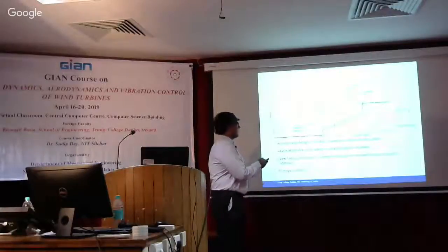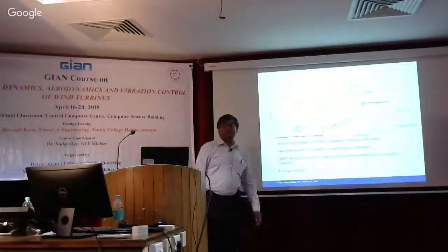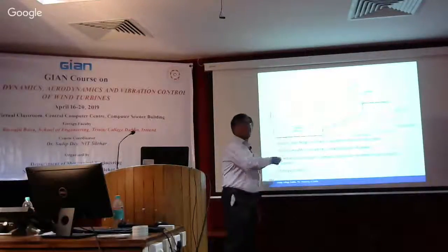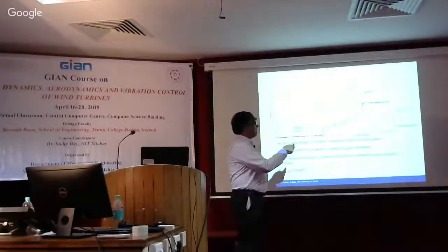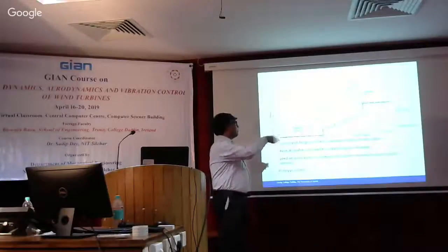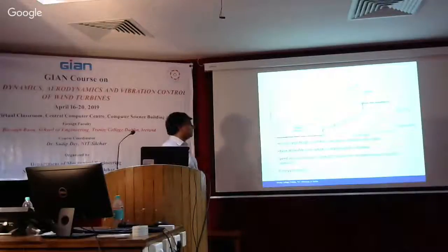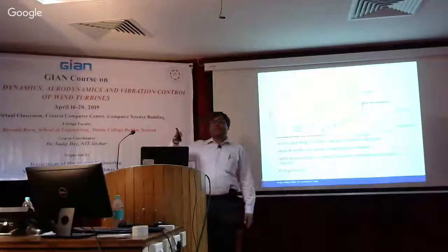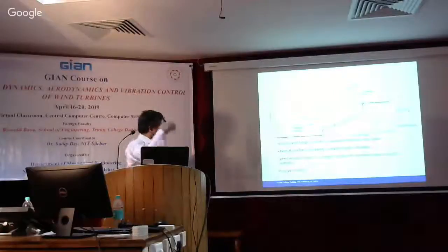So you do not exactly track the curve, but you go to the nearest curve possible, like from here to here, and so on. And normally, with the control system, there's a lookup table which is stored in your control algorithm. So these curves are used eventually to track your input. Also, there is a maximum rotor speed: the tip speed of the blade has to be limited to 70 meters per second for noise consideration. You can't have anything more than that.